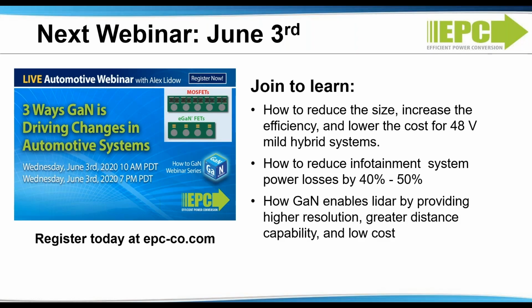If you take a look at how we came up with our 6-volt max on our gates, it really comes down to a desire to have 0 failures ever. If you run our devices at like 5.25 volts, they're fully enhanced, and you will have less than 1 ppm failure in over 10 years. So we're really rating it to make sure that it never fails, as opposed to just rating it because we're taking into account huge amounts of overshoot.